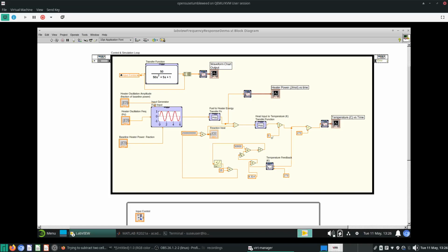So what happened here is that this transfer function actually returns 0 Kelvin to the temperature feedback, and basically we have exponential minus EA over RC, which gives you minus exponential of infinity. Well, technically that should be 0. Well, the solver just does not like that.